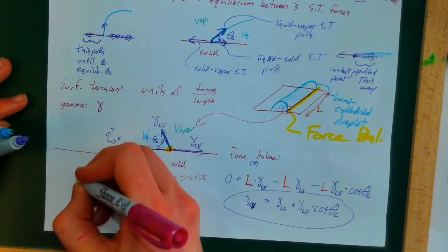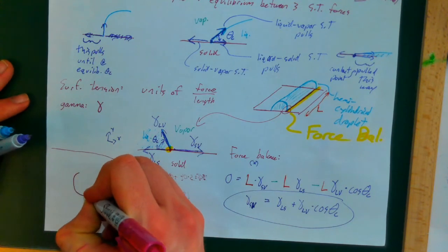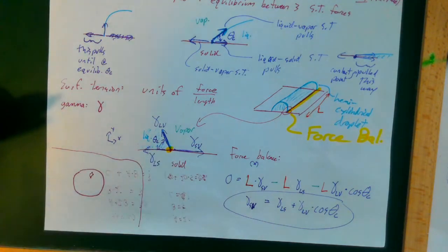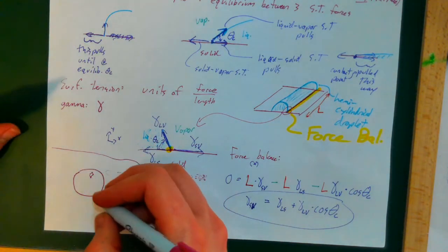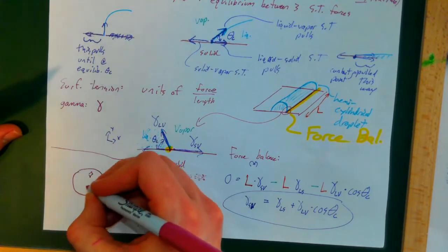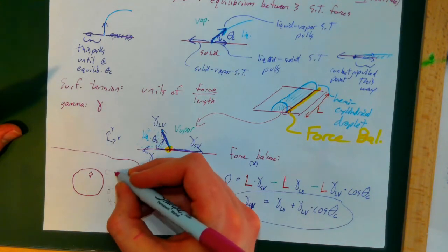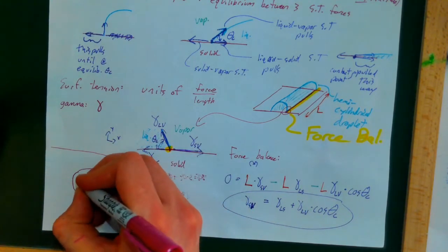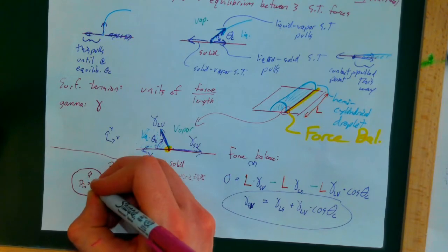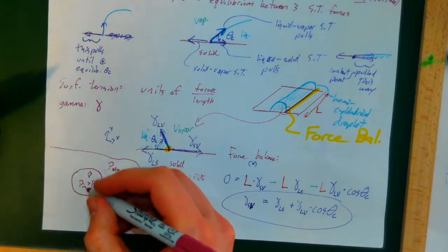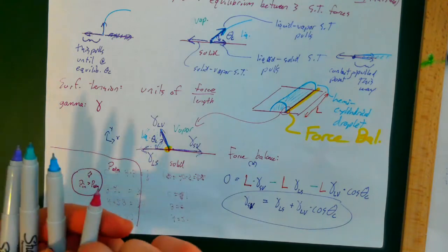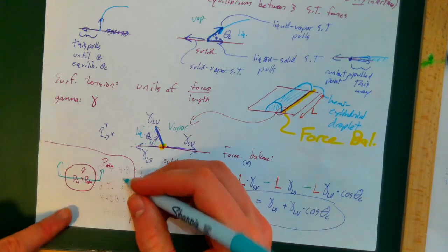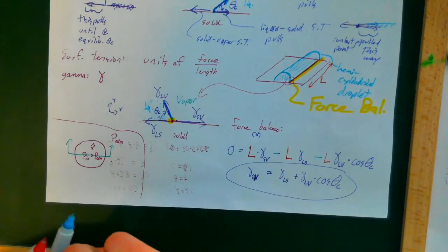If you have a droplet of fluid, it turns out that the pressure inside of this droplet is actually higher than the atmospheric pressure outside, out here. So the P inside is actually greater than atmospheric pressure. Why? Well, imagine if I took this bubble and sliced it like this, and imagine a hemisphere,